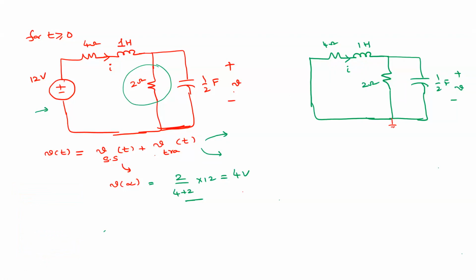So let us assume that. What we have to do is obtain a differential equation with this circuit. In previous classes, when we studied the series RLC and parallel RLC circuits, we learned how to obtain the differential equations, and from the differential equations, how to obtain the characteristic equations. We use that same methodology here. We are interested right now in voltage V, so let's assume that this is voltage V.